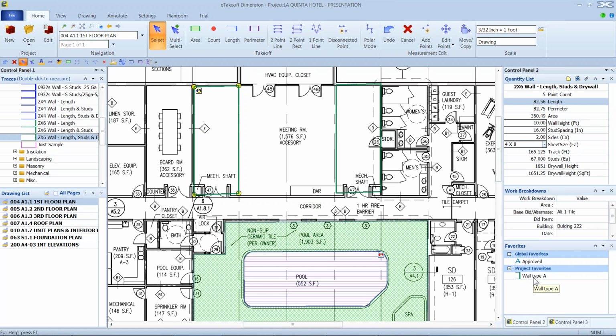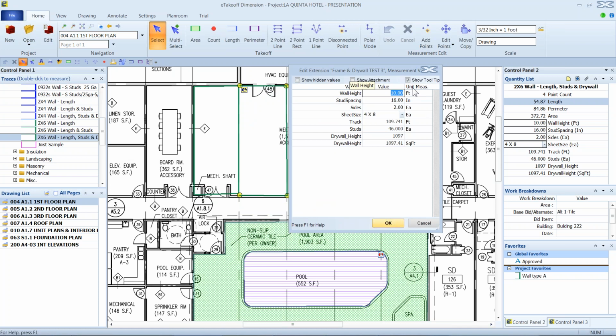And for this project, that is wall type A. We can drag and drop it out there like I showed you, or we can move this into what we call our global favorites, where it will travel from one project to the next. Now, when I use this as a takeoff mechanism, I go through and do takeoff. One thing you'll notice is that E is not being represented as red anymore because we have it already pre-filled for you. Maybe this is a pony wall. We'll just go ahead and enter the differences or the change in that spec, and we're good to go.